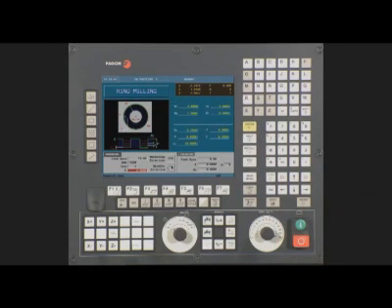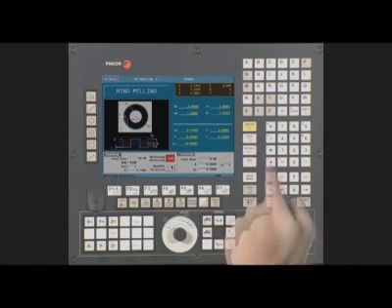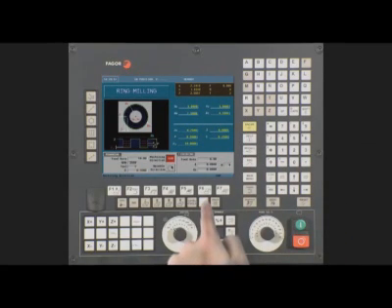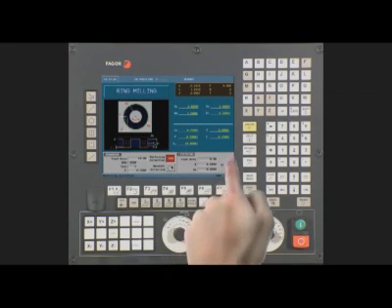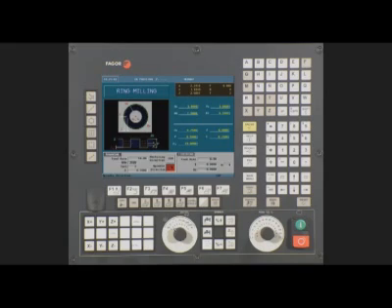Press Enter to continue. This is your milling step-over field. To ensure clean cuts, enter in a value less than the diameter of your tool. In this example, we will use 0.1. Press Enter to continue. Using the half key, select the machining direction. In this example, we will use the counterclockwise direction. Press Enter to continue. Using the half key, select the spindle direction. In this example, we will use clockwise direction.